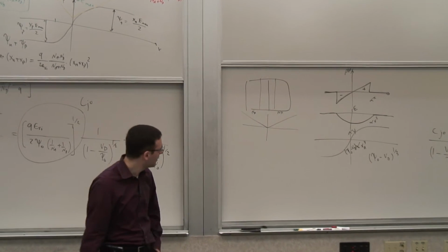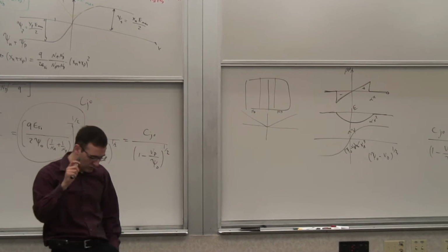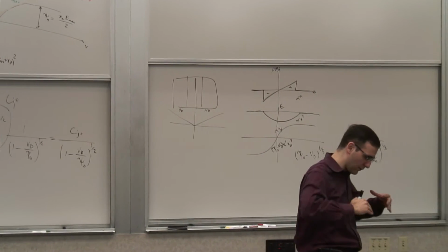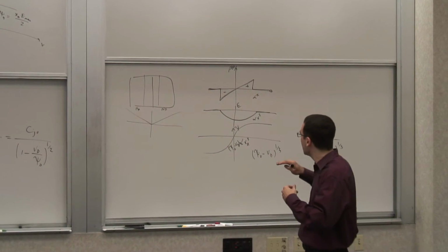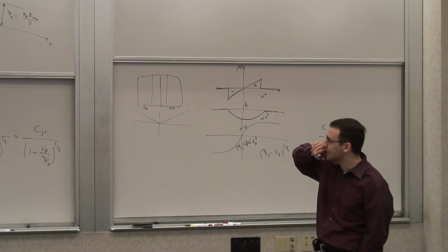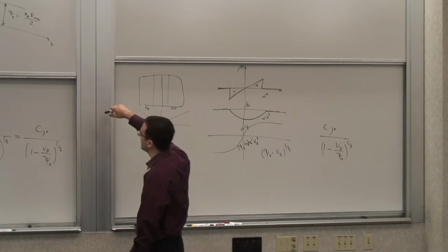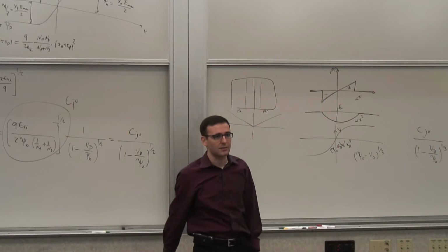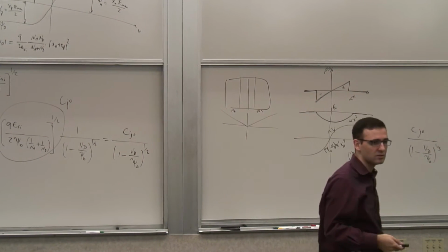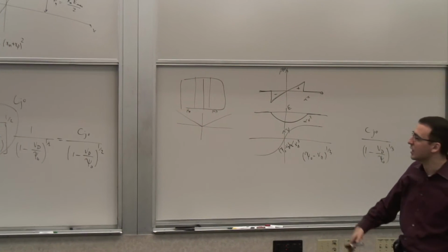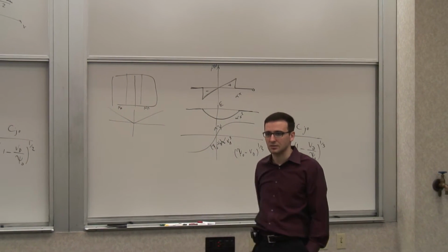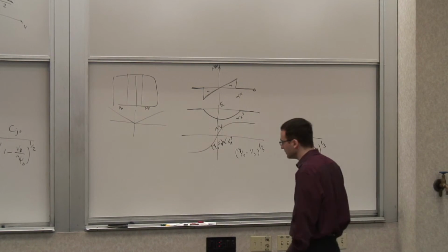Alright, no questions? So we looked at the PN junction, right? So far we looked at it in forward bias, we saw what happens to the current, and we looked at it in reverse bias and we calculated the capacitance. This capacitance, by the way, is quite important. We encounter it a lot in devices, any kind of transistors or diodes and all those things in electronic design. So when you get to the design, it's important to understand what this capacitor is and where it comes from.